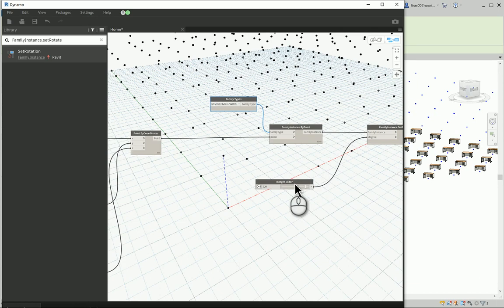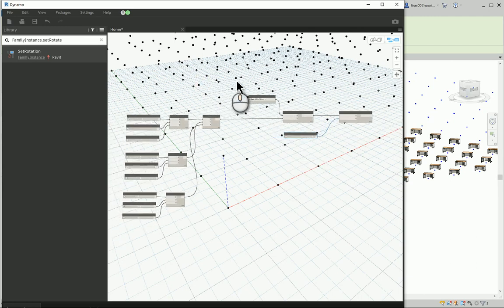That's the point. And the second thing, again, if you change this to Revit conceptual massing or Revit family, some of those nodes and some of the families will not be available, so you might not get the same result. So specifically talking about this example, I'm talking here about the project environment. And again, have a quick look at those two groups.